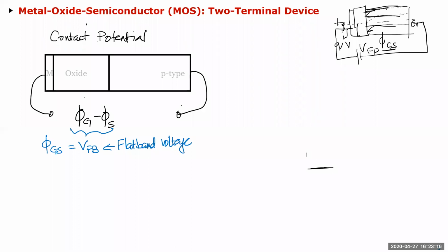Like we were talking last time with Puneet, if I have an oxide layer and I put a metal and a semiconductor, if you had a metal and metal, then you just apply V, you'll get Q. But if you have metal and semiconductor, first you have to apply the contact potential. After that only you can start applying the charge. Otherwise, before that, you actually have a reverse charge here.